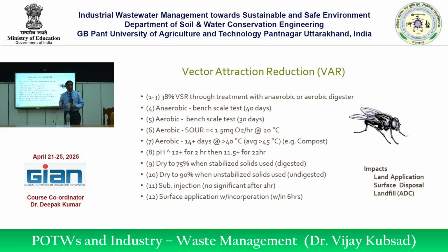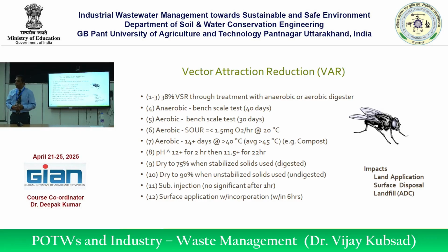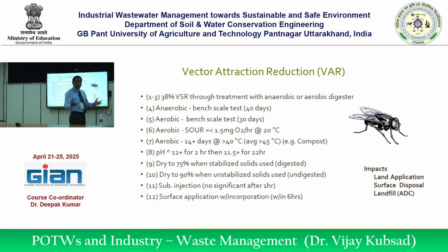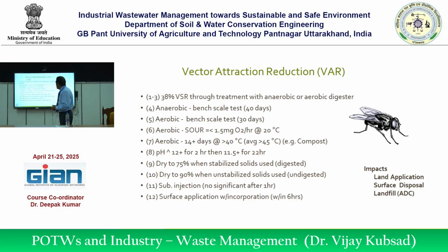A lot of chemicals are sprayed today because this will give rise to a lot of mosquitoes, vectors, and people living around them complain, right? To keep the public calm, they spray certain chemicals, pesticides, on the landfill. But what happens during the rainy season? Slowly it will percolate again, because if they are carcinogenic in nature, that will enter the groundwater, ultimately the river, and ultimately it comes back to the people, right?